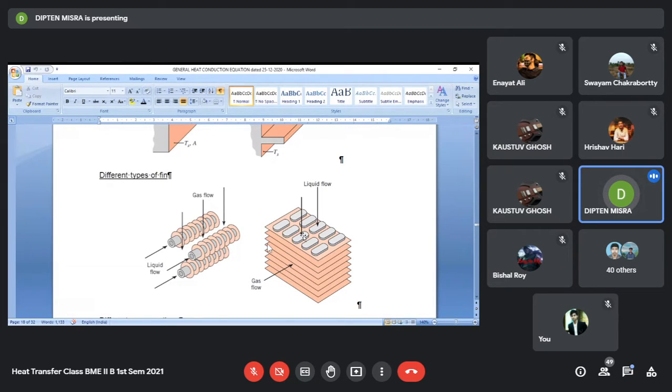If you imagine the tubes are oriented not along this direction but perpendicular to it, then when the gas flows over the tubes, which have a major axis across the flow direction, you see there will be more pressure drop. But if we have the major axis along the flow direction, naturally we can expect the pressure drop to be less. So that is why it is oriented like this.